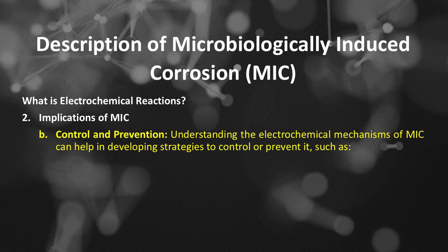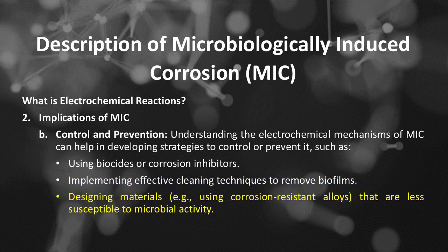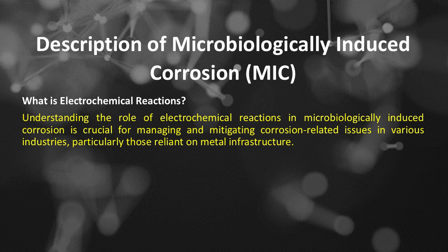Understanding the electrochemical mechanisms of MIC can help in developing strategies to control or prevent it, such as using biocides or corrosion inhibitors, implementing effective cleaning techniques to remove biofilms, designing materials, such as using corrosion-resistant alloys, that are less susceptible to microbial activity. Understanding the role of electrochemical reactions in microbiologically induced corrosion is crucial for managing and mitigating corrosion-related issues in various industries, particularly those reliant on metal infrastructure.